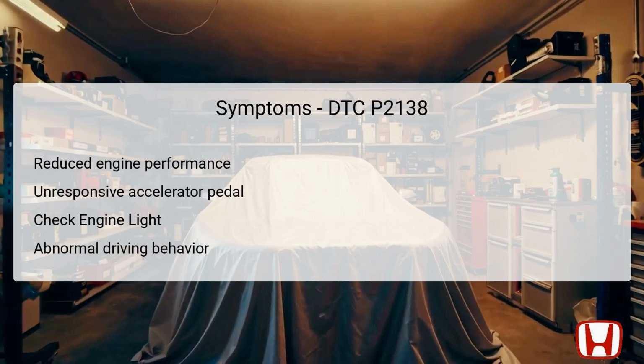When DTC P2138 is triggered, various symptoms can manifest, which impact vehicle performance and driver experience. One of the most noticeable symptoms is reduced engine performance. The vehicle may not accelerate as expected due to the erroneous signals sent to the ECU. Additionally, drivers may notice an unresponsive accelerator pedal, which can hinder normal operation and cause safety concerns.